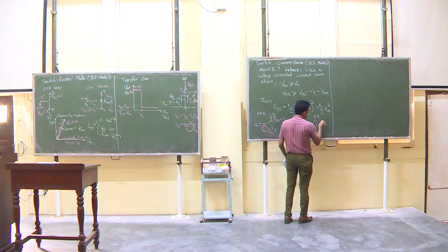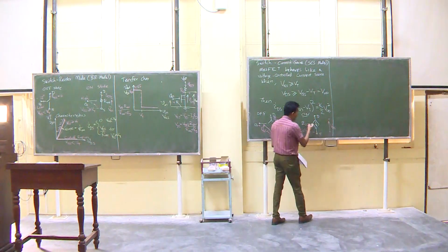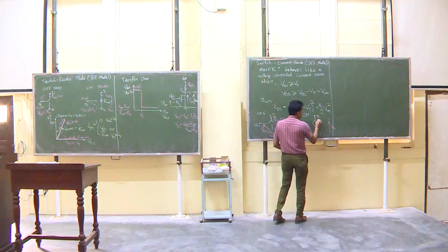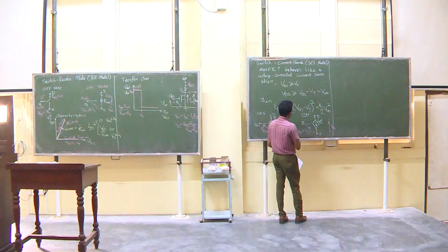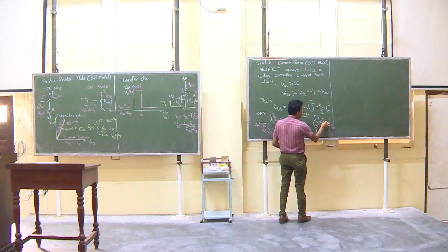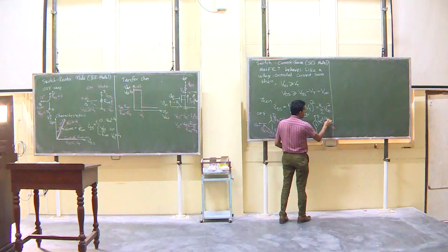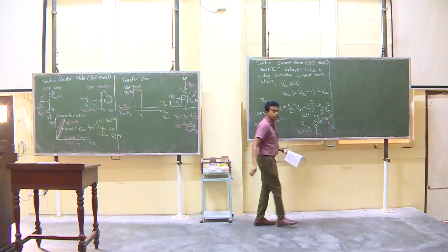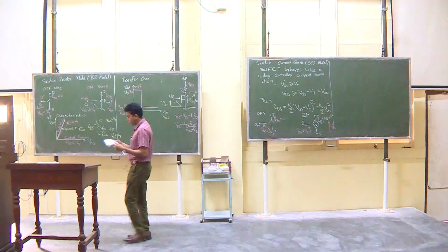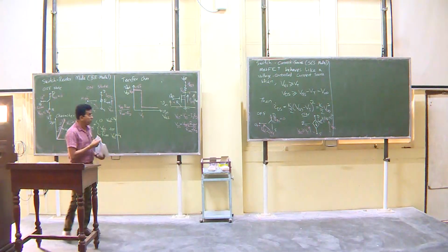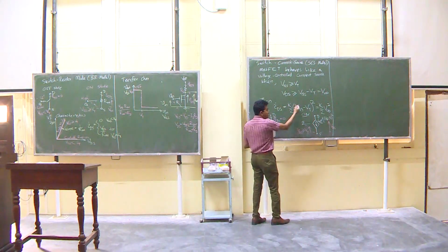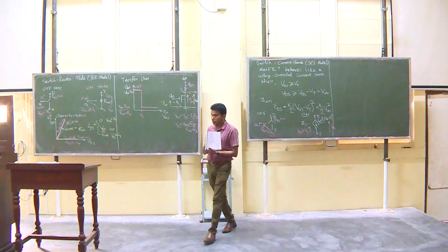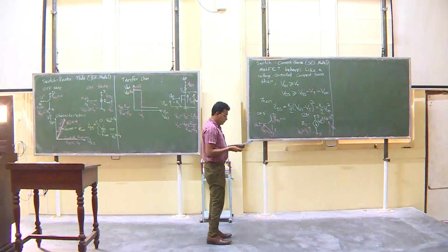The output voltage is VDS and this current IDS is equal to this equation, K divided by 2 times VGS minus Vt squared. So that is the relationship. ID is a function of VGS, and the others are constants, correct. That is what we have there.